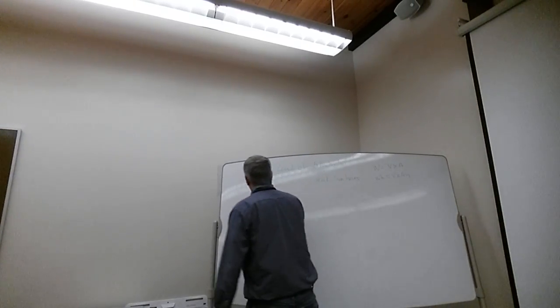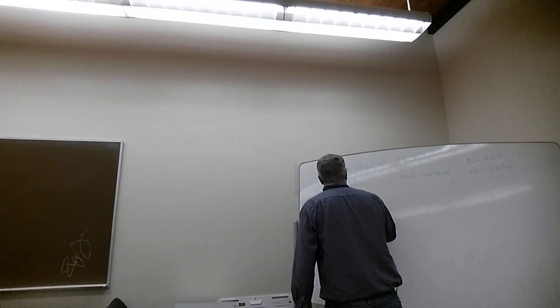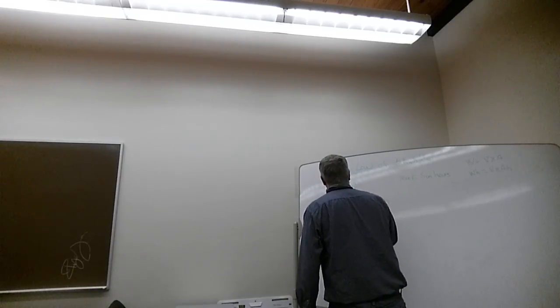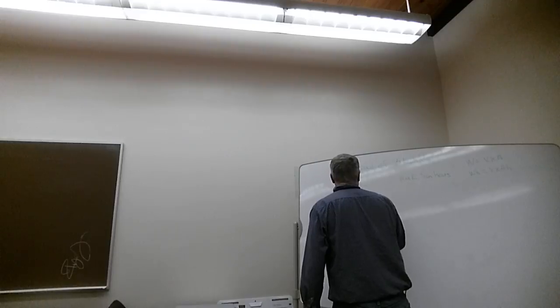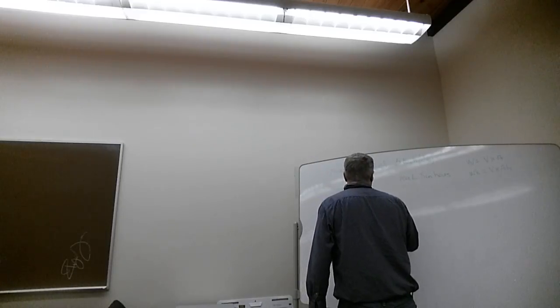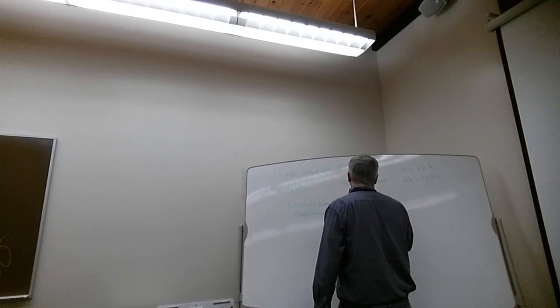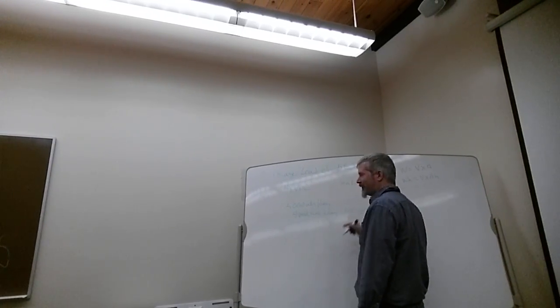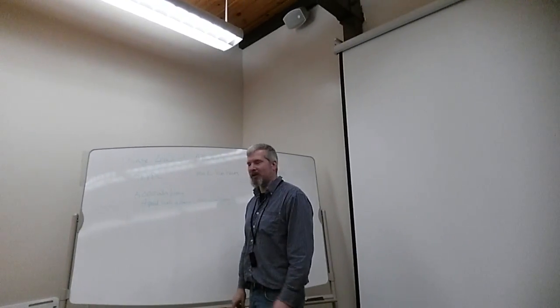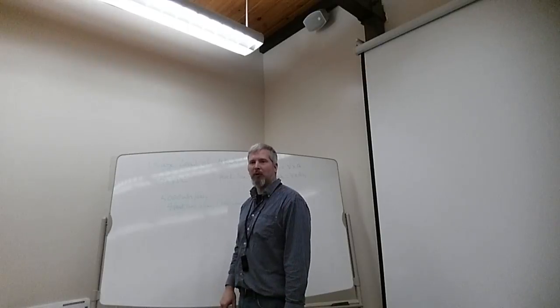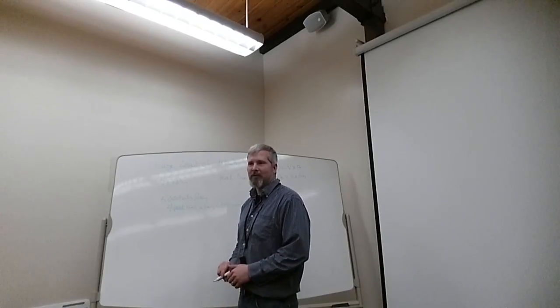So if we take 5,000 watt hours a day, and we divide it by 4 peak suns a day at 1,000 watts per meter squared per day, that's what that value of a peak sun hour is. We're essentially taking 5 and dividing it by 4,000. Does that make sense?